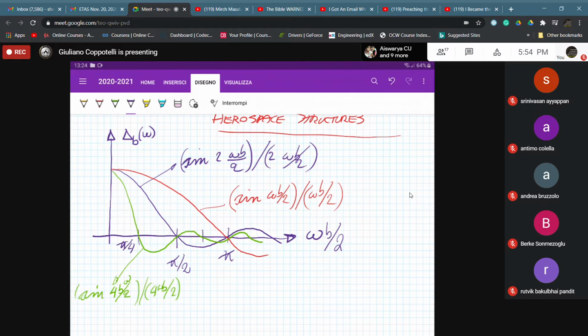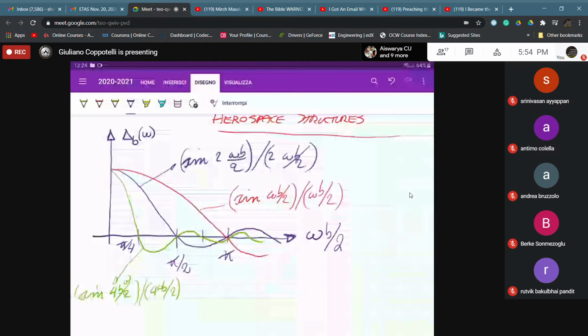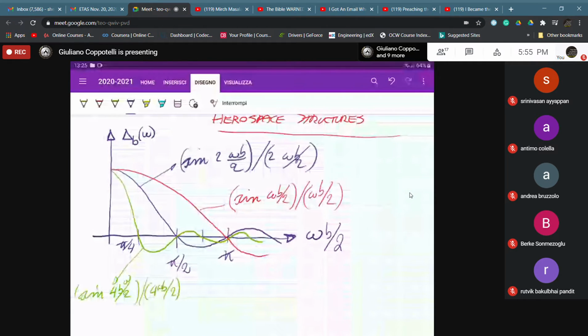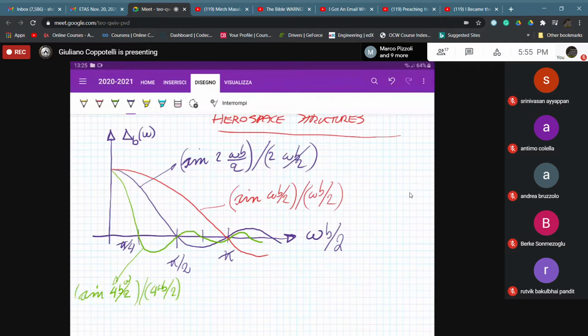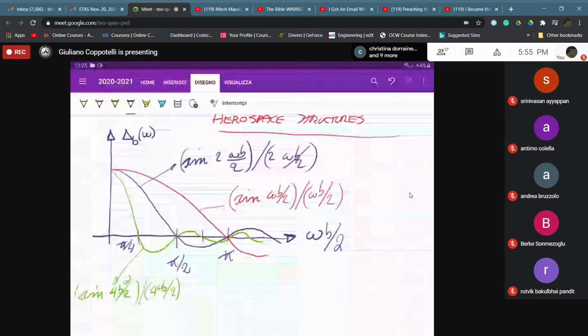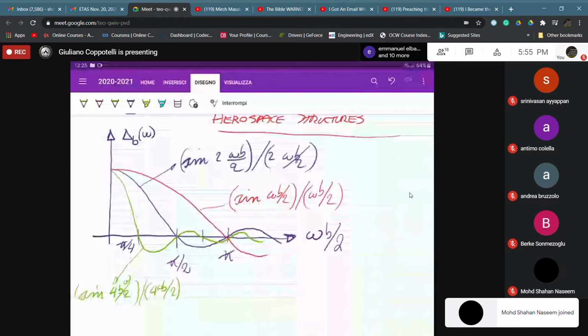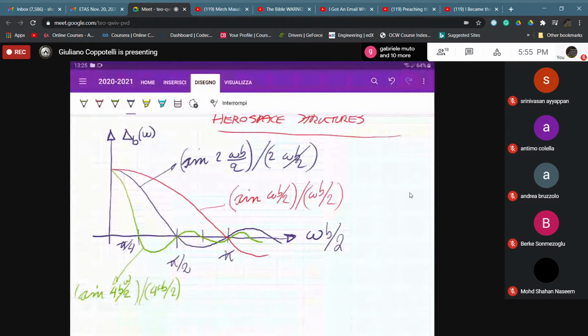As we can see there, now let's see how we can use those plots in order to have a practical use of the hammer. What we have to do is start with a hammer configuration in terms of mass, in terms of stiffness, and then prescribe how much is the acceptable attenuation of your signal.